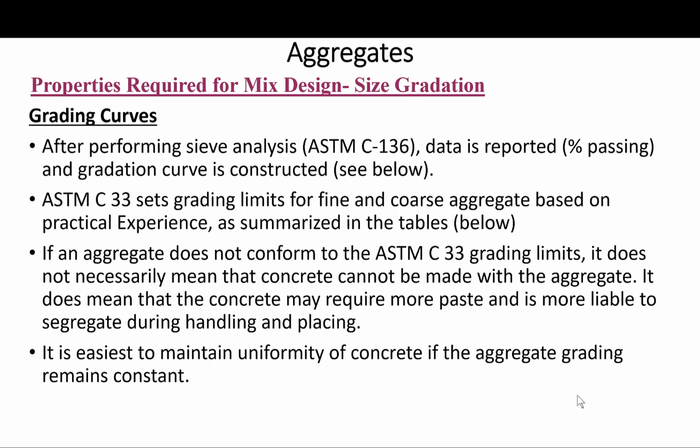On large jobs, where considerable quantities of concrete will be required, it may be advantageous to blend several fractions of coarse aggregates to maintain uniformity of grading. This is a common procedure in ready-mixed concrete plants, since concrete can be produced more economically when corrections of the grading variability are eliminated. So the key is you want to maintain uniformity. That's the key, uniformity.